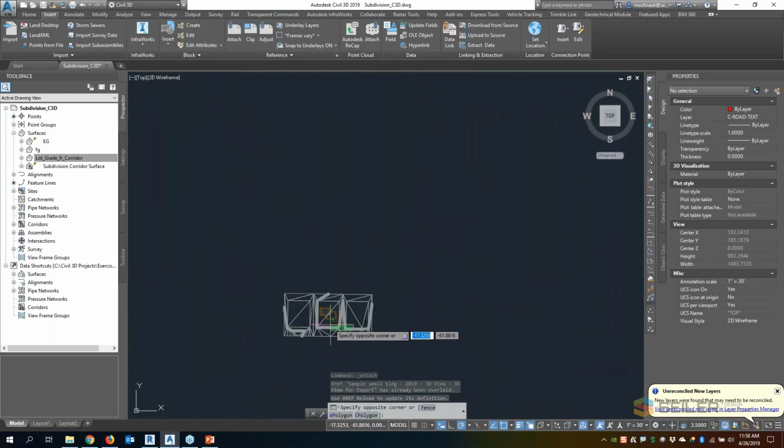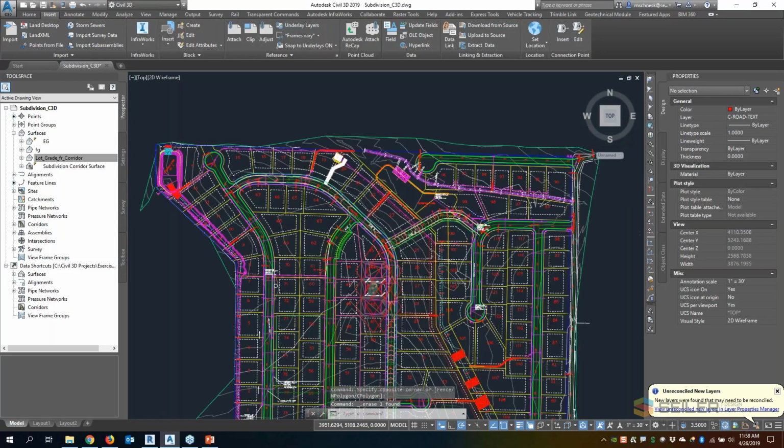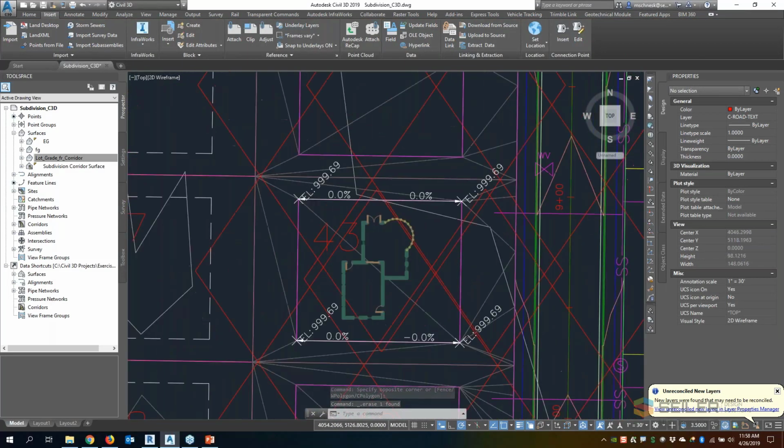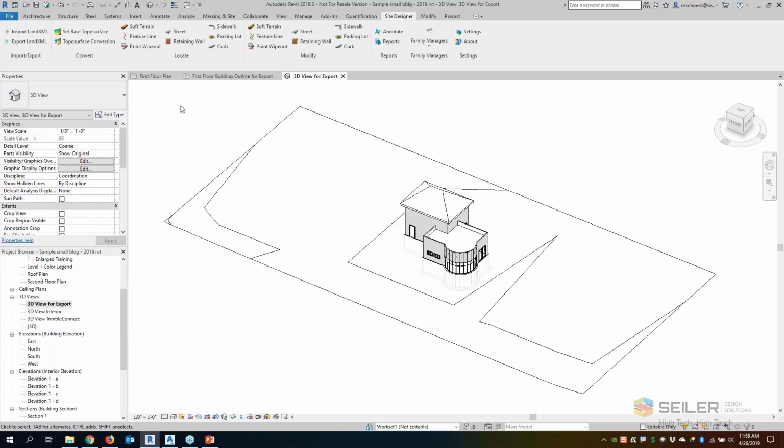And now it still came down here. Okay, well, I guess I'm having some issues with that one. Technically, it's supposed to come in here, and maybe it's the way I had it set up, or I didn't save something, or I did not overwrite properly. But just make sure that when you export out from Revit that second time that you set it up to make sure it uses the shared coordinates when it exports. And that's what I have for this webinar.